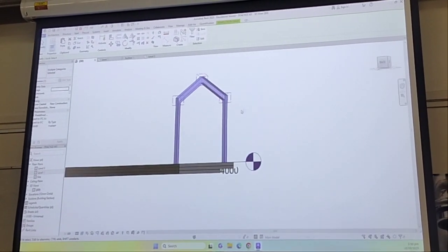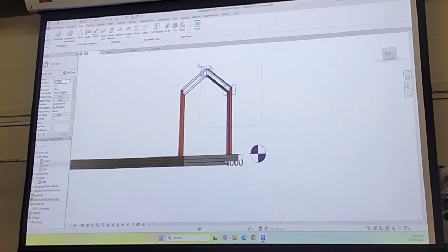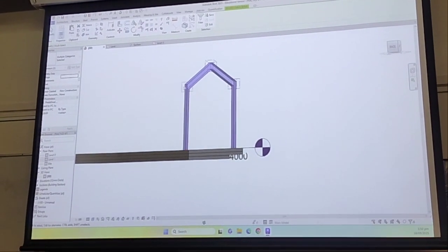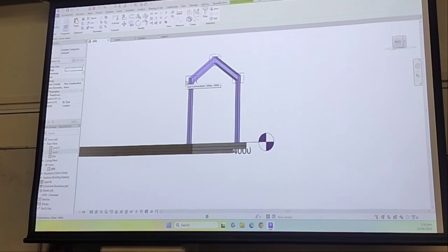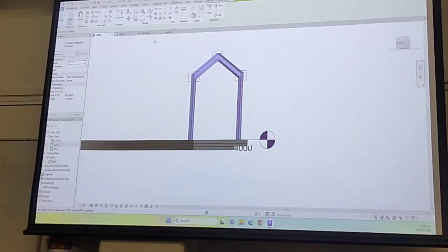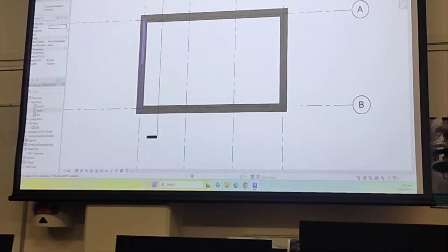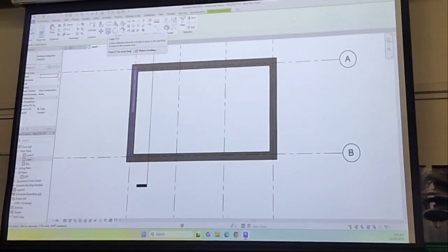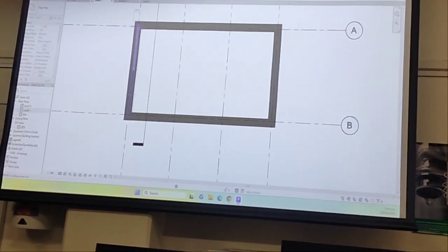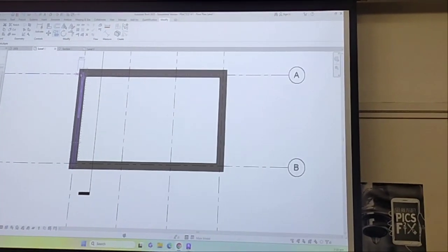Make sure that when you're copying it, you also copy the connections. If I leave out one connection, for example this miter, it won't have that connection when I copy paste. So make sure you copy paste everything, and just Control C, or just leave it here, and then click this one, up to you. So copy, and now we want to copy it to the 4 grids that we have.